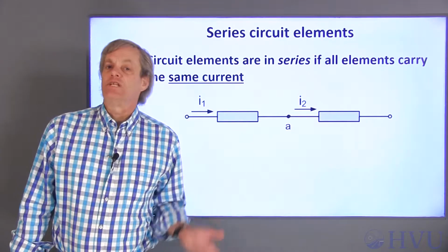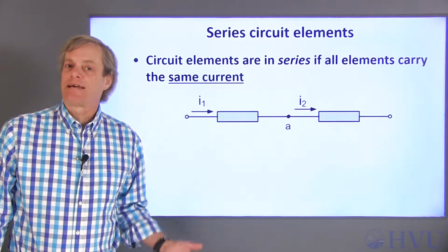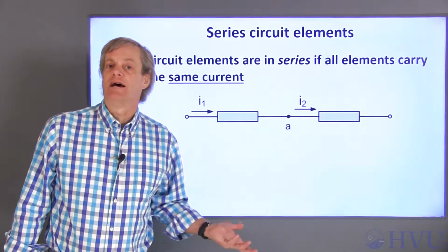In this video, I'll introduce series resistors. Then we'll look at some simplifications to our circuit analysis that can result if we have resistors in series in our circuit. By definition, series elements share exactly the same current at all times.